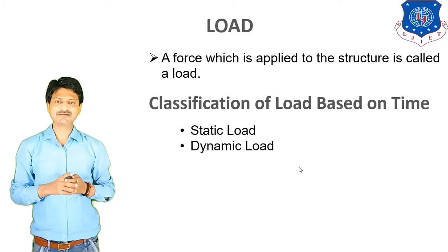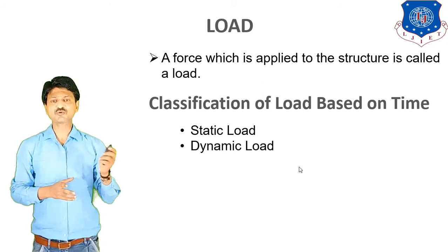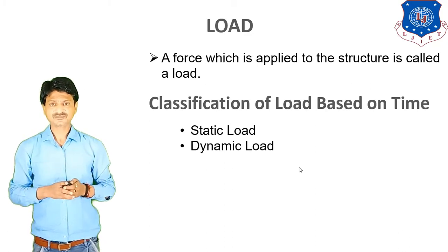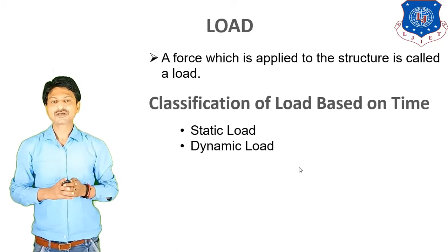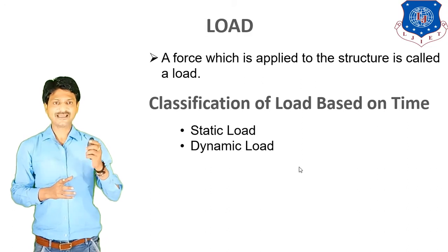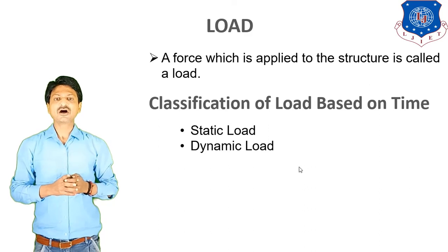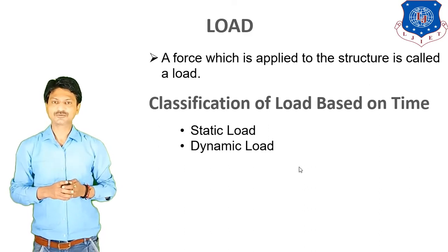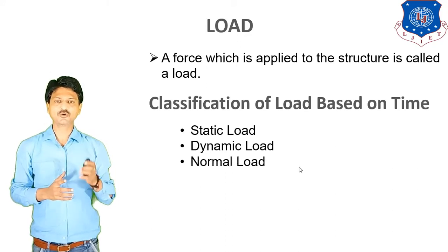Next is dynamic load. It is exactly opposite to the static load. In dynamic load, the load varies with respect to time. So we can say that the magnitude of that load continuously varies with respect to time. Wind load and earthquake load are examples of dynamic load.